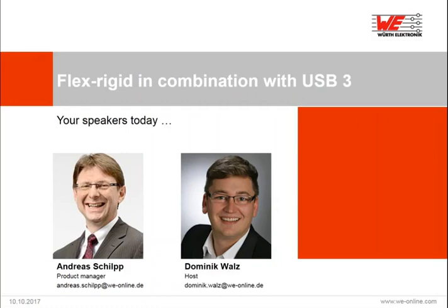On the other hand, if we have Flexrigid technology, we always have very small and compact solutions. So until today, we have never had problems with signal integrity issues. There is a limit definitely regarding cables, for example for USB 3. The cable maximum is allowed to have 1 meter without repeaters. So 1 meter is a long way for a PCB. So in that way, we never had problems with Flexrigid PCBs.